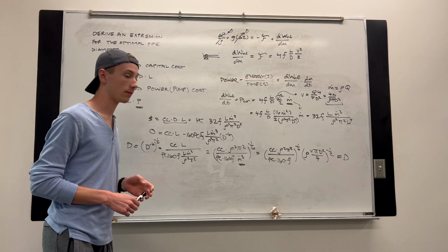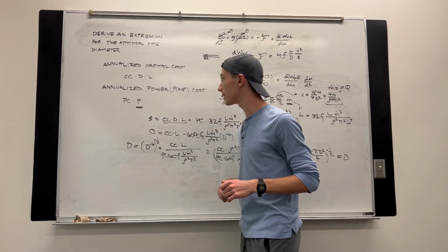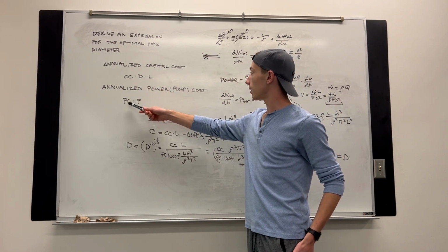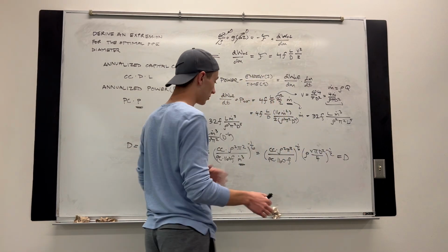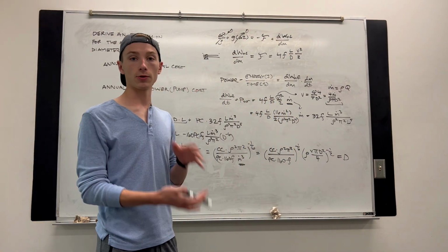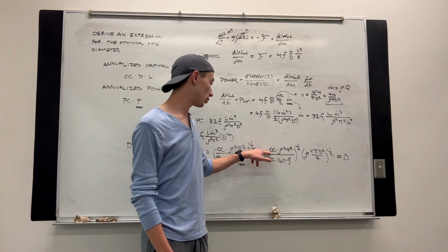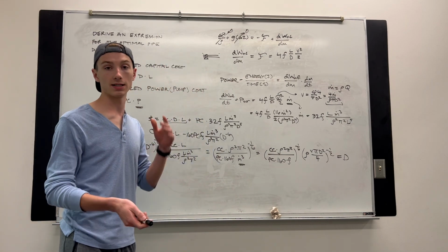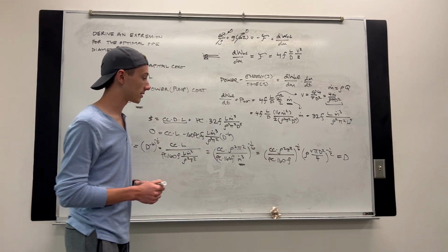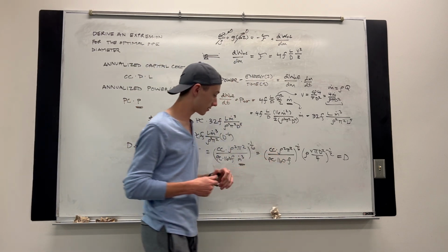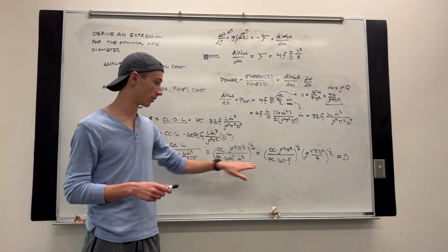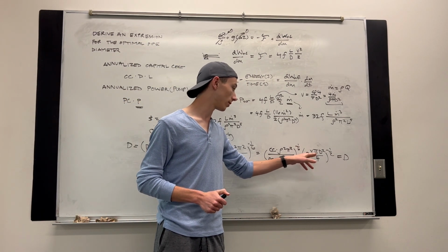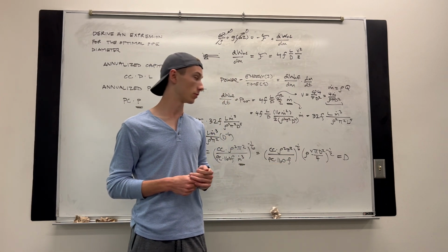This is interesting, and it actually works because when the capital costs and pump costs increase or fluctuate with the market, they change proportional to one another. So when the capital cost increases by some amount, the pump cost usually increases by about the same amount, or vice versa when they decrease, right? And so this constant, that CC over PC value, really just stays about the same. And so, yeah, that optimal velocity, if you solve for it, is pretty much always around 2 meters per second.